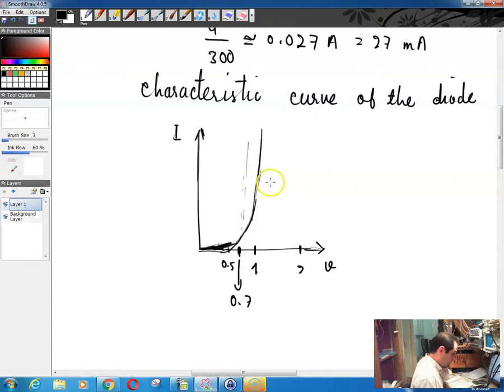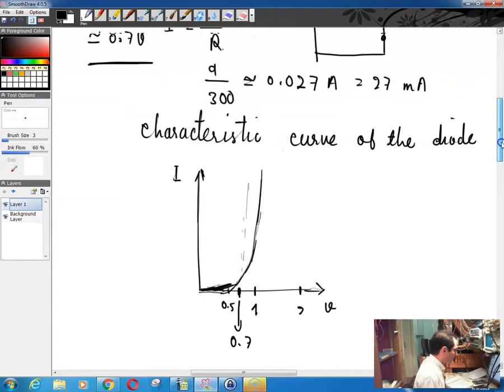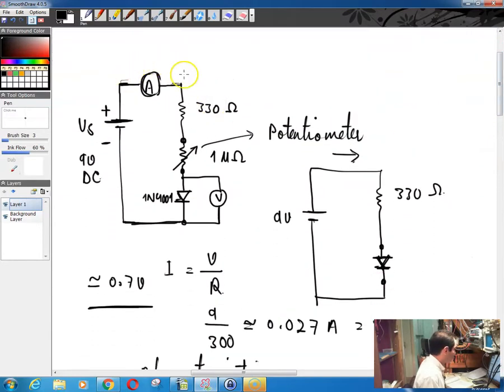So now in order to see this practically, what you need to do is create some sort of circuit like this, meaning that you need a simple 9 volt power supply. You need an ammeter to see what sort of current is going through your circuit, and you need a resistor here, for example a 330 ohm resistor, which basically limits the current in your circuit, and I'm going to tell you why it's going to limit the current.